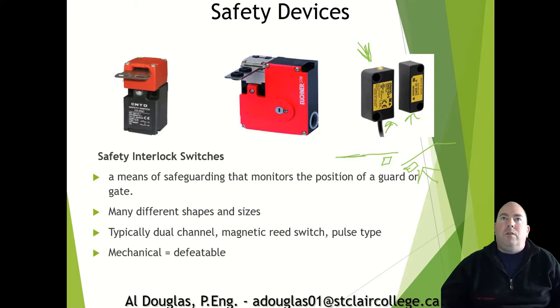The other way you can do this is you get these ones with a little metal key that actually plugs into the rest of the gate switch. You can see that key there. And you mount that onto the part that moves. Two different types here. This larger type here probably has a solenoid that actually locks this in place. So if you want to open that door, you would actually need to request that door becomes open, and then it will actually open the door for you.